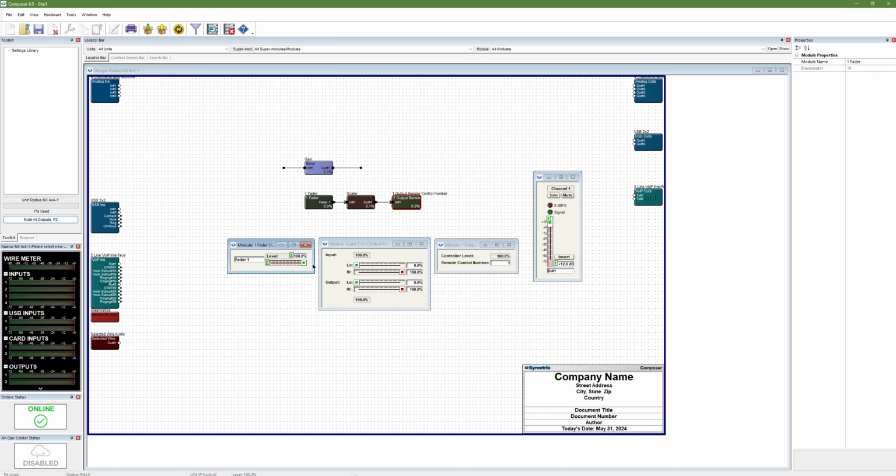We can allow the control fader to fully scale on the scaler's input. But if we adjust the output to a desired degree, we can limit the movement of the gain fader. In this case, we'll set the low output to 50% and the high output to 85.7%. This will give us a range of 0 to -30 dB. The scaler out values can be adjusted to match your system requirements.